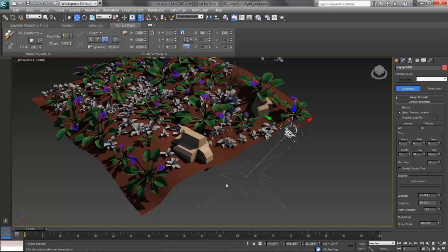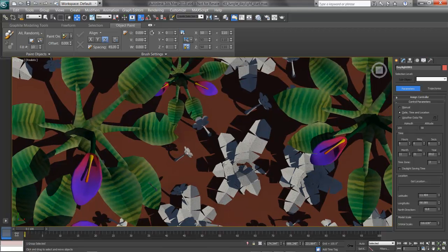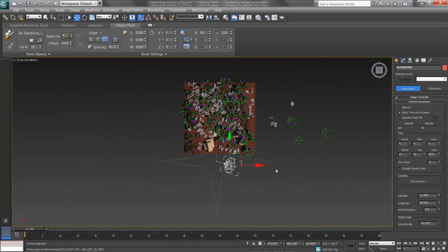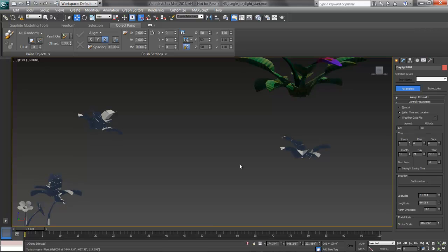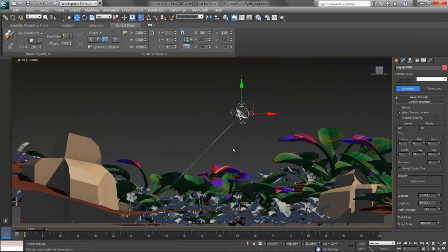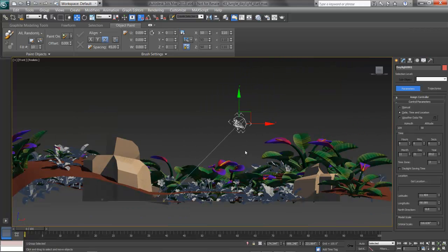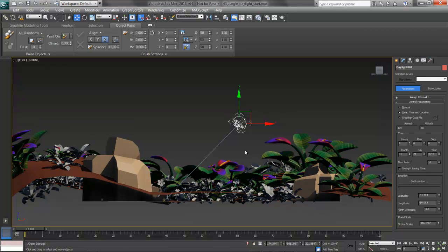If I view it in a top view by hitting T and zooming out, the daylight is angling across and not at a 45-degree angle. If I go into a front view and press Z to zoom extents, I see the same thing. The daylight is angling across the scene, and again, not at a 45-degree angle. This way, any adjacent surfaces, such as those on my rocks, will show clearly differently lit, and I'm getting long reach out of the shadows and sunbeams in my scene.